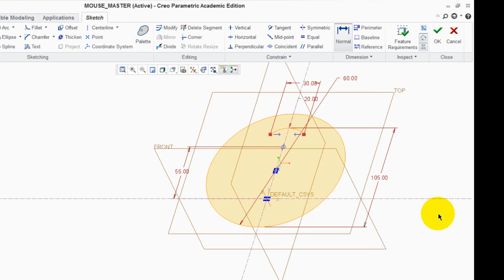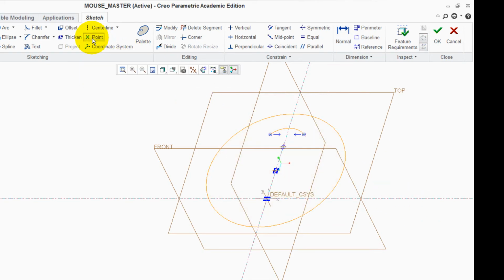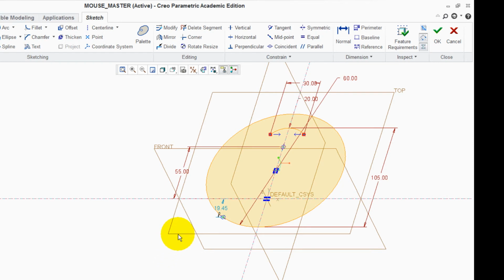And again, we can now put 2 points onto the arc. Select the point command. Move it down onto the arc somewhere, not allowing it to snap, but to just put it anywhere here. Left click once. Middle mouse. If it's still selected, you can mirror it straight away. If not, drag a box.